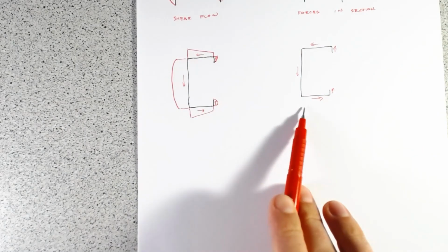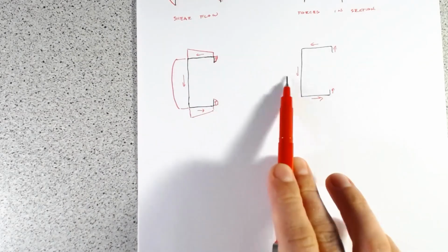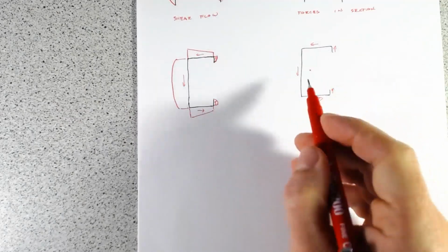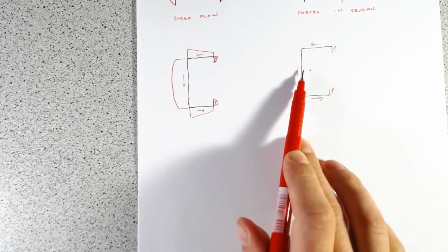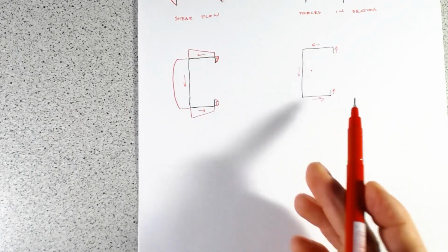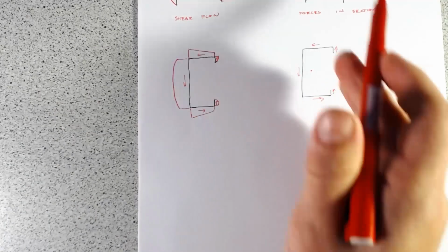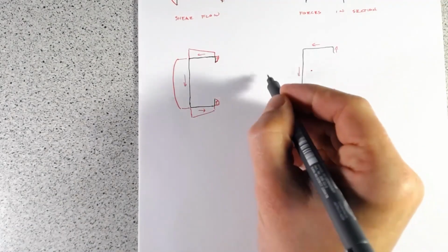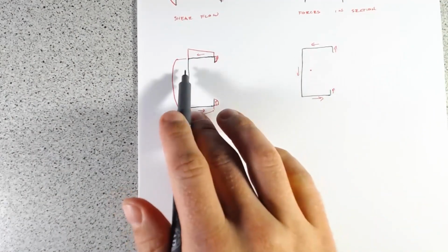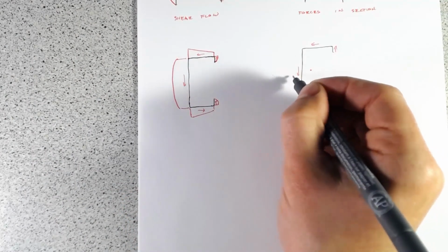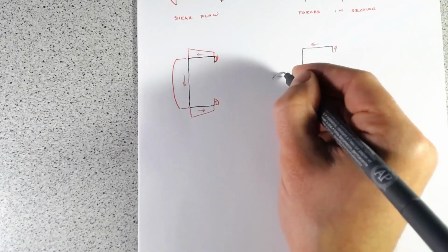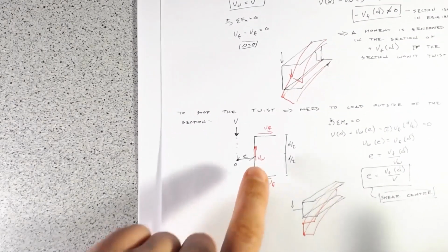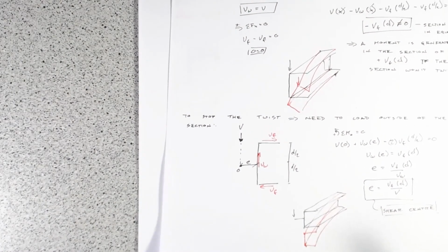Well, you can see now the presence of these little forces. If we take a moment about this part, it's gotten even worse because now we have the contribution of these two little forces on the ends also wanting to make it spin around. So you find that with these channels with little flanges, the e gets even bigger than for e here with a channel with no flange.